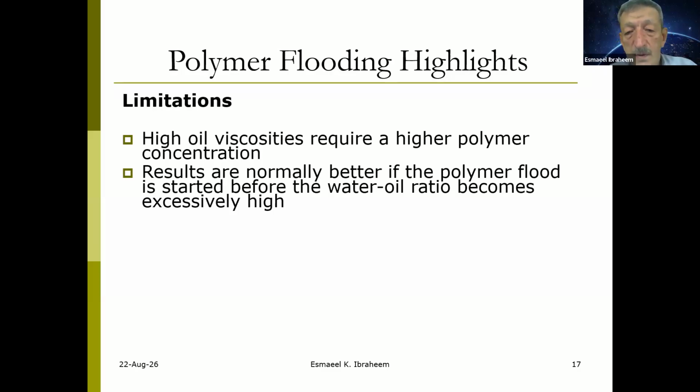High oil viscosities require a higher polymer concentration, and results are normally better if the polymer flood is started before the water-oil ratio becomes excessively high. We need not to be late in applying the polymer flooding. So the best time is when the water-oil ratio is not very high. Maybe you will have some water with the oil, but you should not let the water-oil ratio become excessively high.